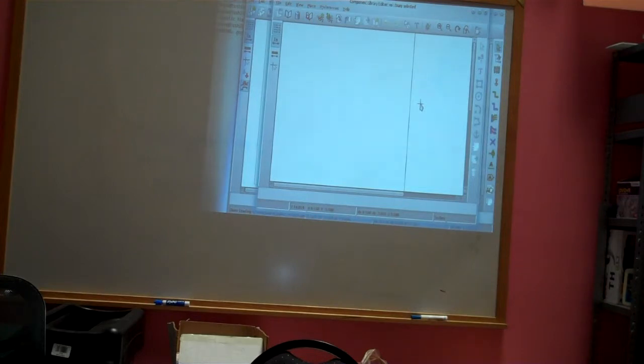Now, I need to explain that libraries in KiCad I don't find intuitive. Okay? For me, the intuitive thing to do is you create a library that's empty first and you start putting things in. And that's not the way it works in KiCad. The way you create a library is you actually have to create a component first, and then you will create the library to put it into. The other thing is you can work with an existing library.